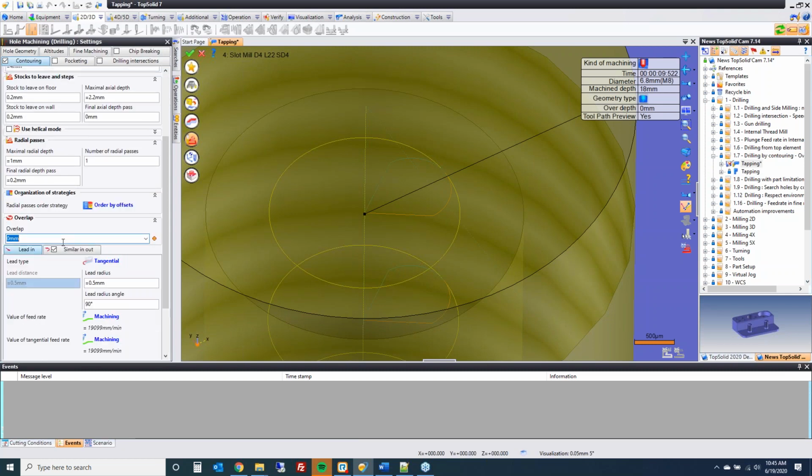All right, it's right down here. So I can go here and say I want a 0.5 millimeter overlap. And notice now you have your control of overlap. The function existed in regular side milling. It just wasn't put in here before for some reason. Now it is. So again, subtle little control, but a good clean improvement also.